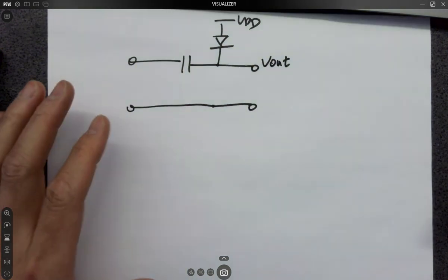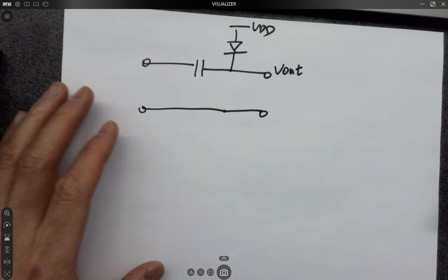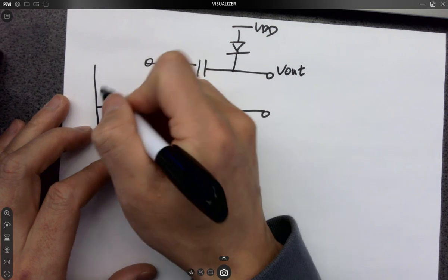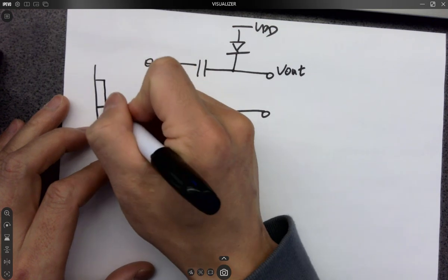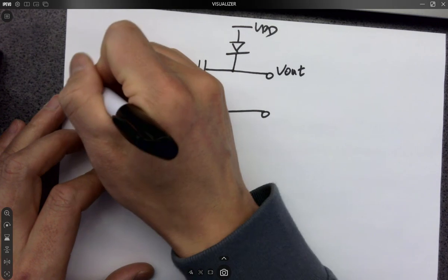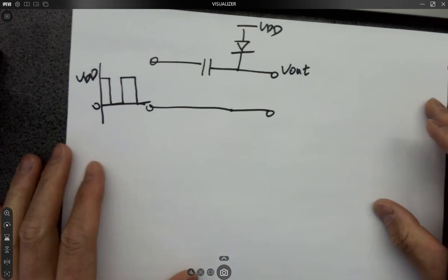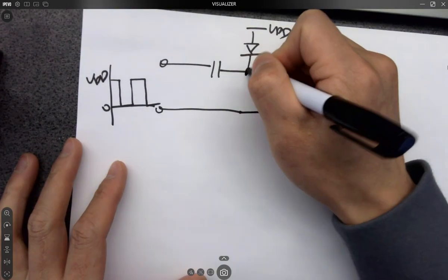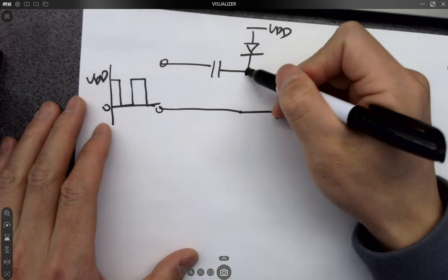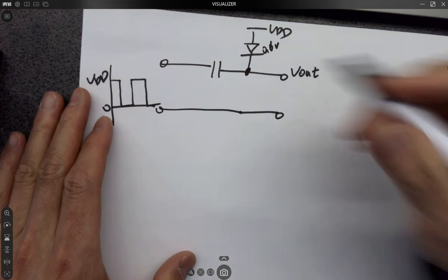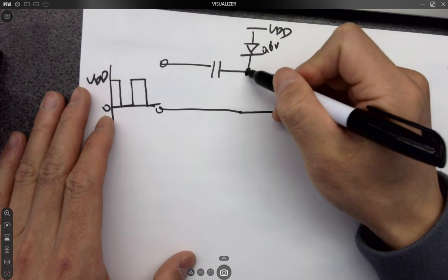We're just repeating whatever we cover on Monday, okay? So if I have this one oscillating, because it's a digital signal, the digital signal doesn't have negative voltages. So this has to be oscillating from 0 to VDD, like this, right? Logic 1, logic 0. So what is the range of the voltage here at this point? If there's a 0.6 volts voltage drop across the diode, what's going to happen to this point? What is the voltage range?